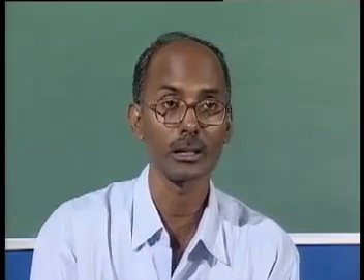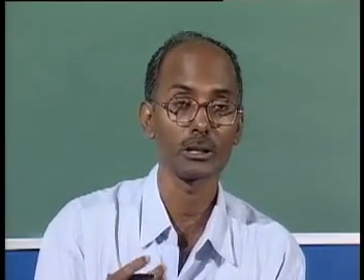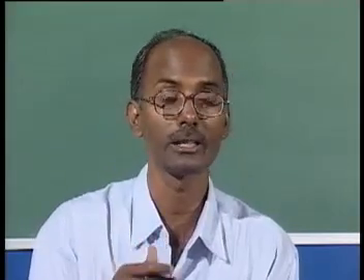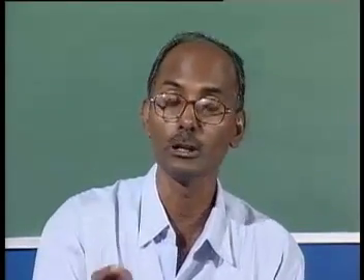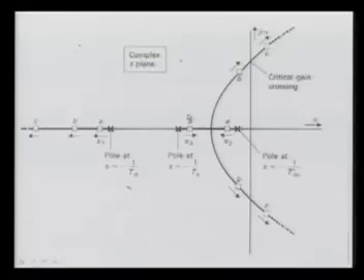When compensation is required, there are two types of compensation, series or feedback. In series there are lead, lag, or lead-lag together, and then feedback. Lead is used because it improves the stability of the system. We also saw that if one of the poles is cancelled, the locus will be vertical and will not cross the imaginary axis, so the system will be purely stable.